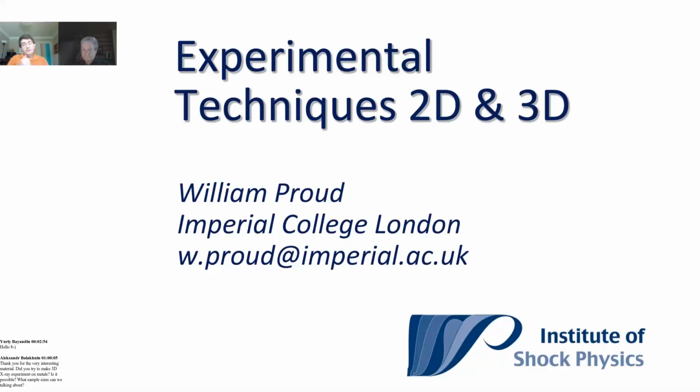We've used X-rays for that, and also high-speed photography looking around the edge, because when you expand the cylinder, we can vary the strain rates along the cylinder, and that made it particularly interesting looking for the growth of fragmentation and the speed of deformation and how fast the crack moved in that material.